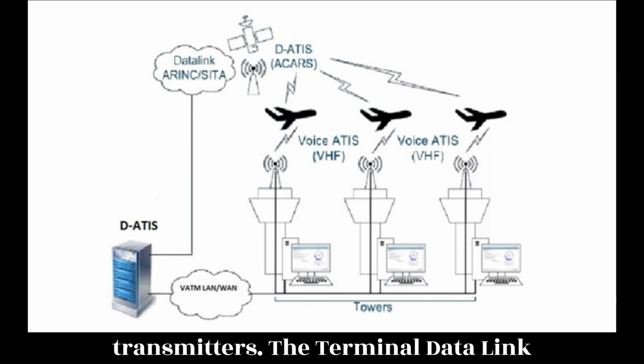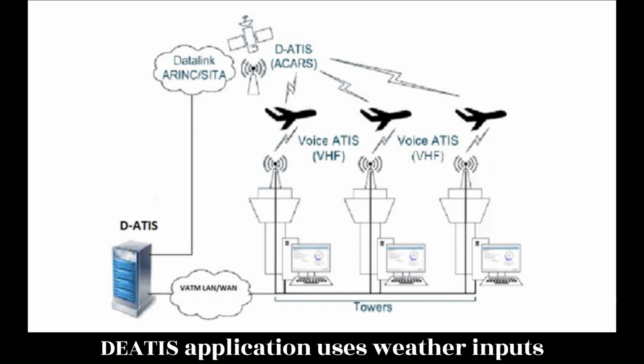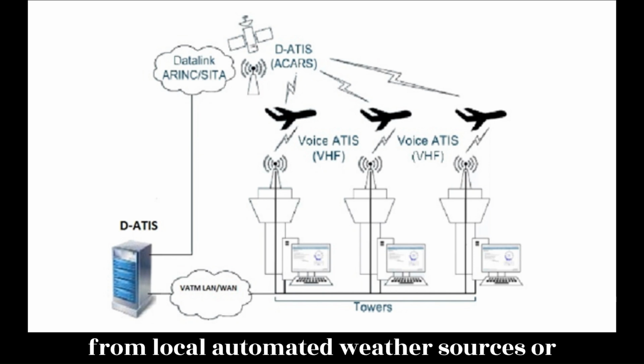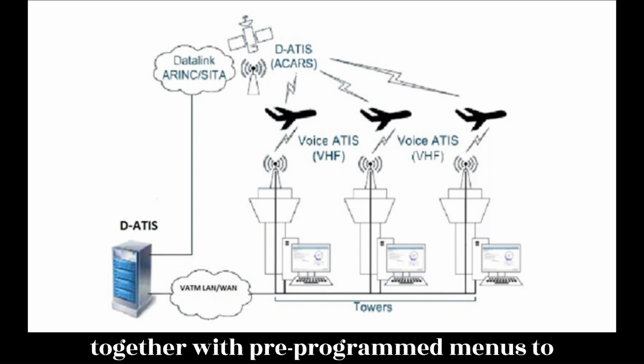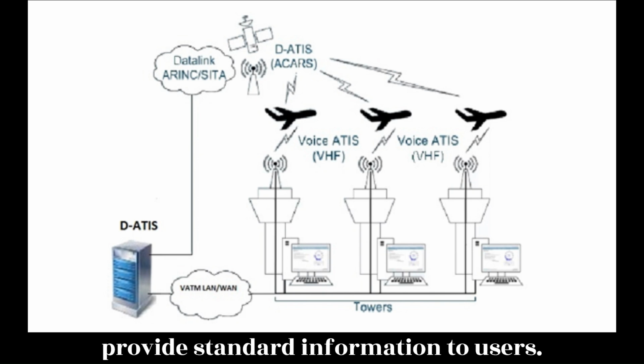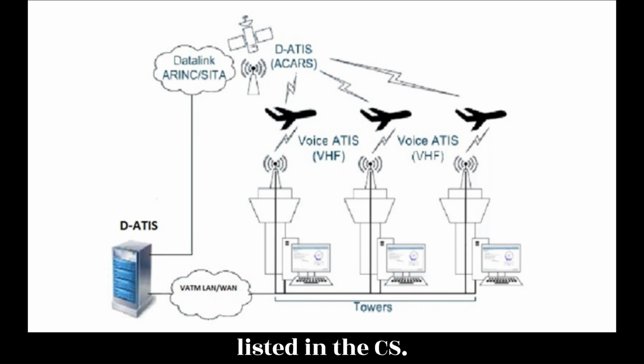The Terminal Data Link System, TDLS, DATIS application uses weather inputs from local automated weather sources or manually entered meteorological data together with pre-programmed menus to provide standard information to users. Airports with DATIS capability are listed in the CS.